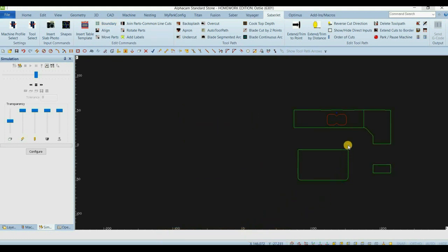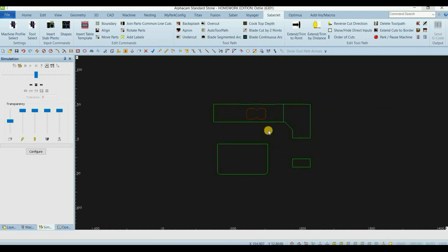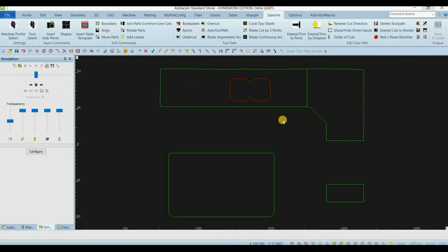The copied geometries will now be joined and closed, and in the geometry layer. The boundary command turns off show breaks. Be sure to turn it back on if you need it. If there was a seam drawn in, the cut has now been fabricated. The same rules apply for a seam line as when using the cut command. They must touch or bisect the geometry on both sides.